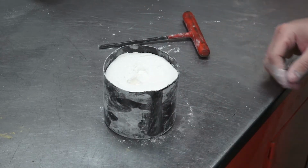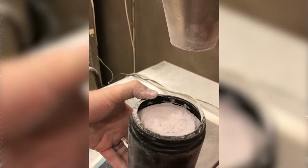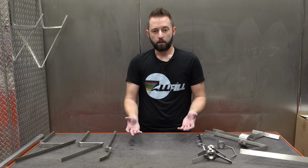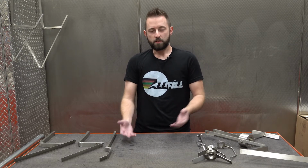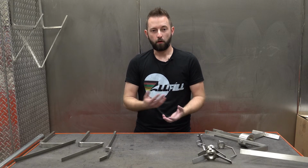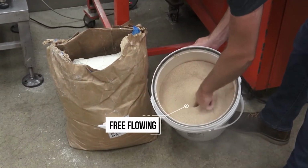So you can load a hopper full of a powder. That powder, when it's unagitated, will actually settle, compress, and densify on itself, causing the product to become very non-free flow. But once it's agitated, it aerates and becomes fluid, almost like a liquid. And that changes it to more of a free-flowing characteristic.